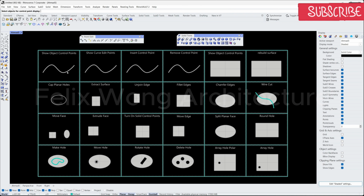Choose Show Object Control Points, select the curve, press Enter. Now move the control points to adjust the curve shape. Click on Show Curve Edit Points, select the curve, press Enter. Move the curve edit points to change the curve shape.